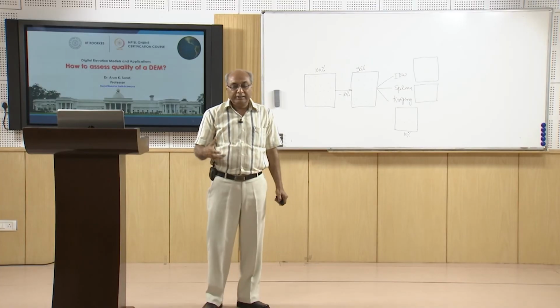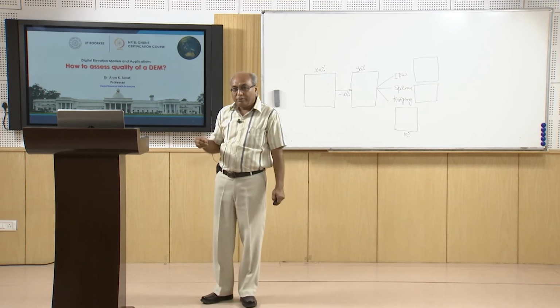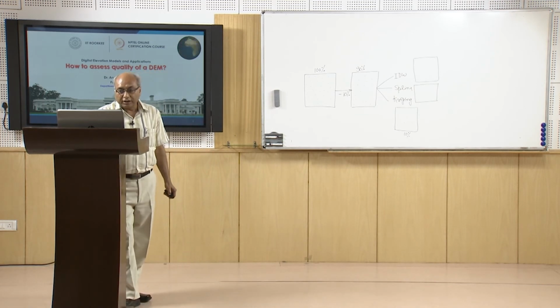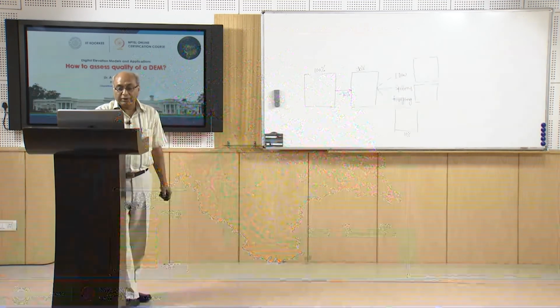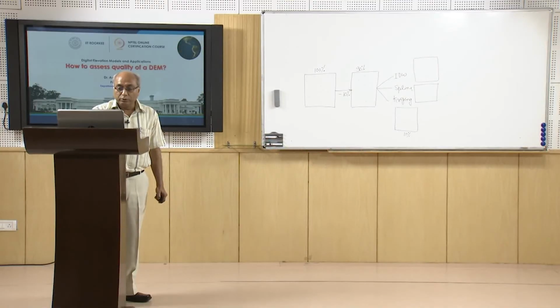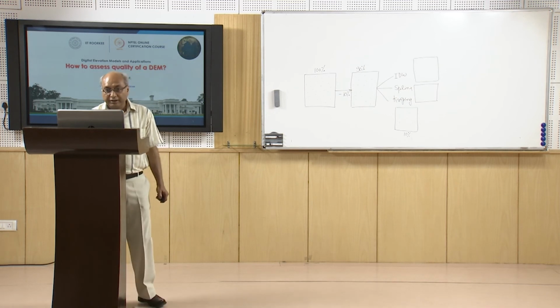While these radar images were collected for snow covered or glaciated areas, no data was collected because of some shadow or some dielectric constant, and therefore these voids, which are represented in this example in dark maroon color, were assigned a very wild value so that we can declare to the system that whenever it encounters this value, in this case minus 32,768 meter, it should consider it as no data and not involve it in any calculation whenever this value is encountered within a data file.